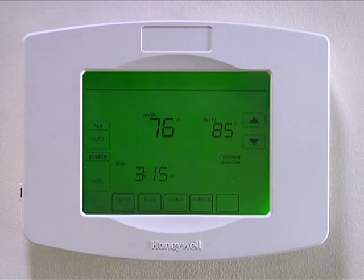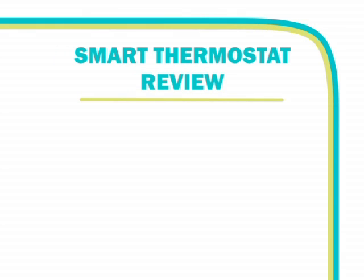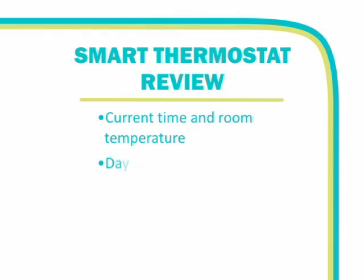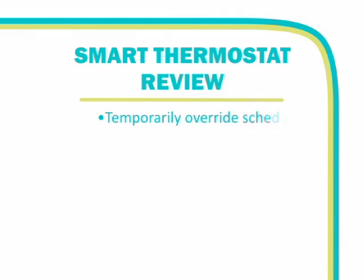Once you have completed programming the smart thermostat according to the customer's pre-temperature chart, be sure to introduce the customer to the following smart thermostat displays and how to manage the features and settings. Current time and room temperature. Day of the week. Fan on, auto, and circ features. System selection for off, cool, and heat. Temperature up, warmer, and down, cooler arrows. How to temporarily override the scheduled program. 5-year battery life and how to replace the battery if needed.